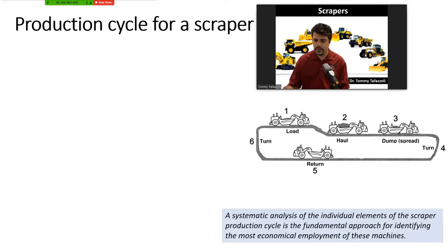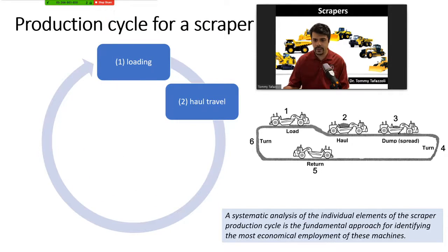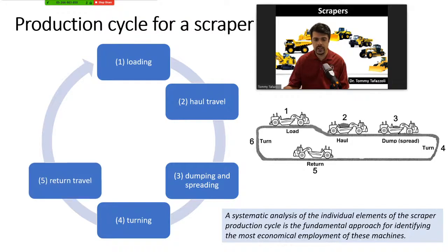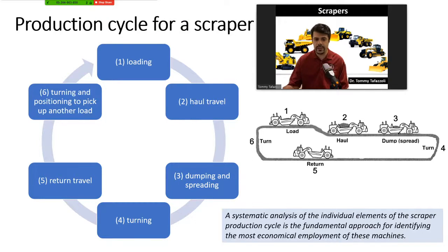So this completes the loop. So we have to consider loading, haul travel, dumping and spreading, turning, return travel, and turning and positioning to pick up another load.